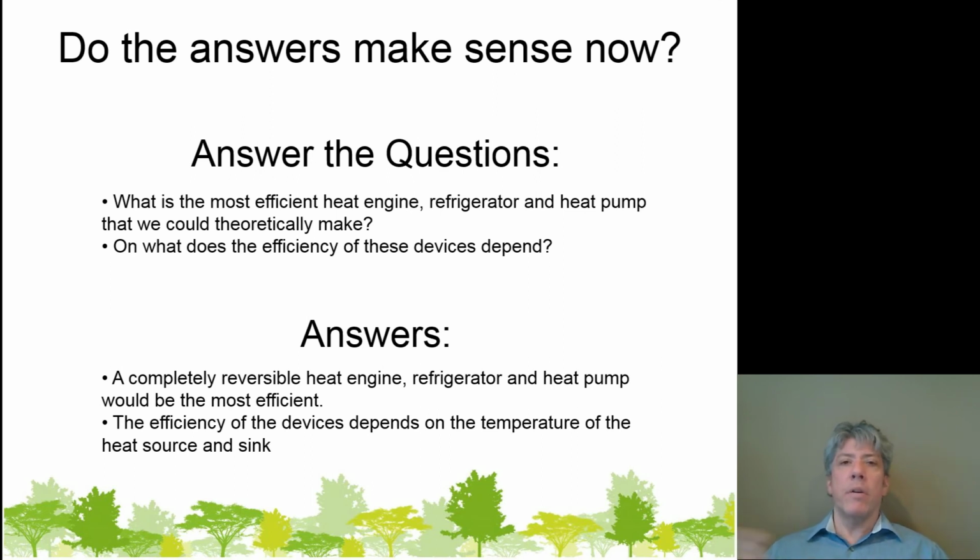How could we increase the efficiency of your car's engine, for example? The low temperature sink is the atmosphere. You're not going to change the atmosphere's temperature, right? That's just not going to happen. I know that global warming is a concern. I know that there are seasonal variations. You as a human being can't just dial up the thermostat tomorrow. If we could, we'd probably get out of this winter stuff pretty quick, and we'd probably dial it back in the summer a little bit. But we can't, right? So whatever the temperature is of the atmosphere, that's just the sink temperature. That's the best we can do.